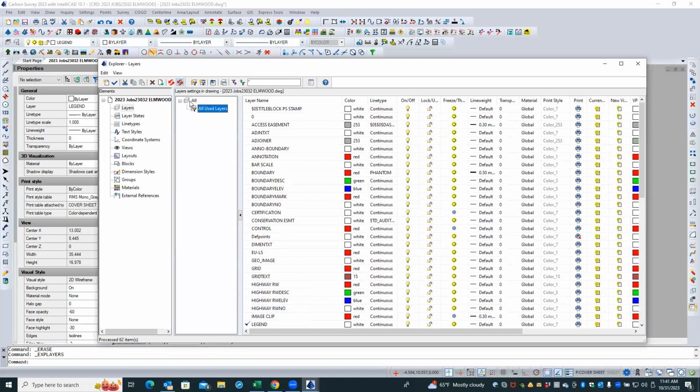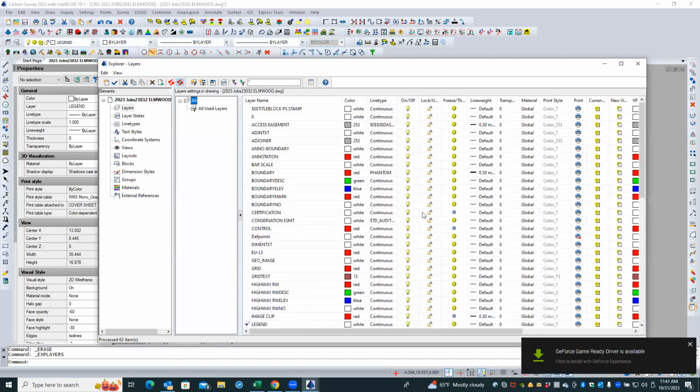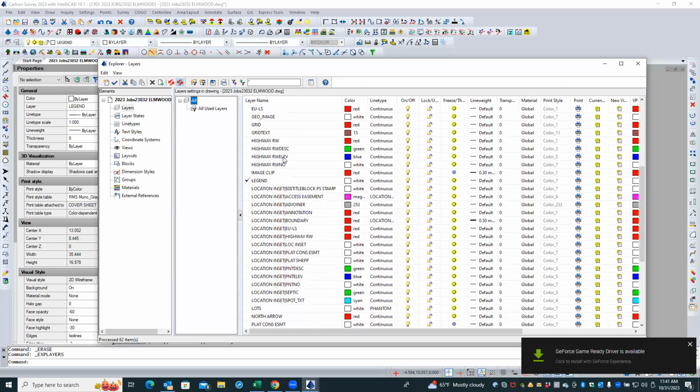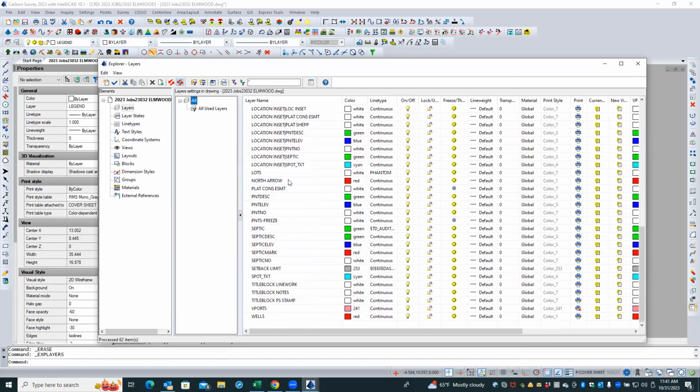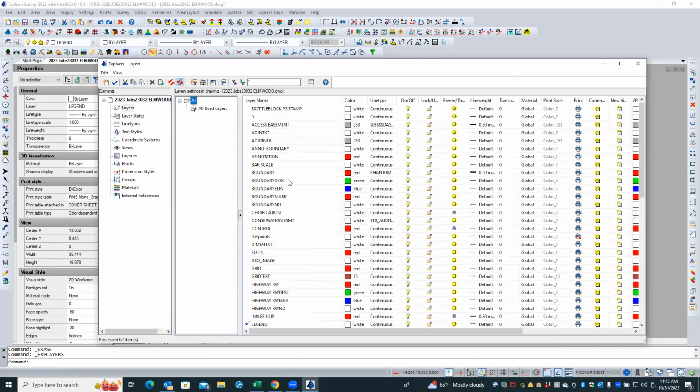There could be others, so let's look at all layers. Any layer names that have that vertical bar in them are coming from XRefs. Looks like you don't have any other ones, so you're okay. You've also got names with a $0 in them; those are also coming from external files.